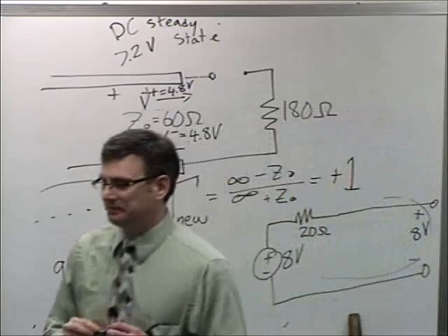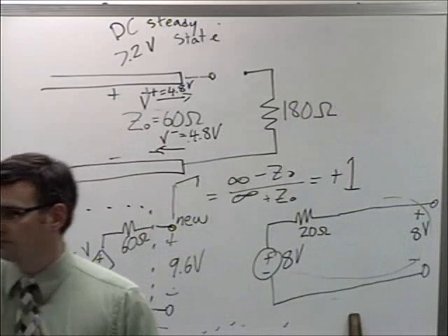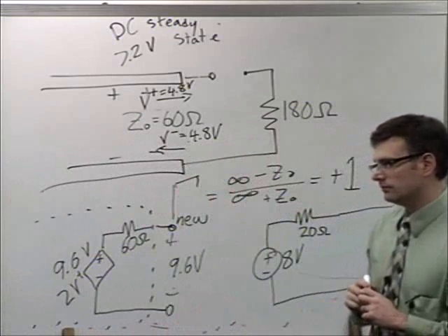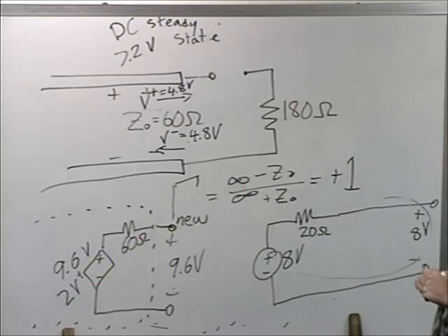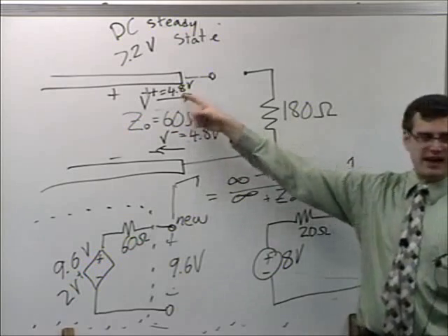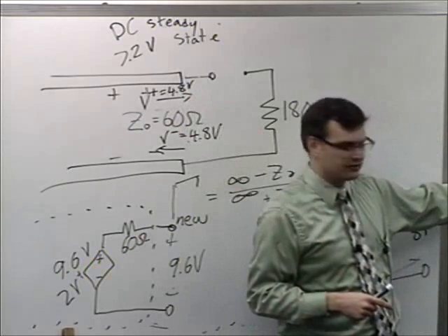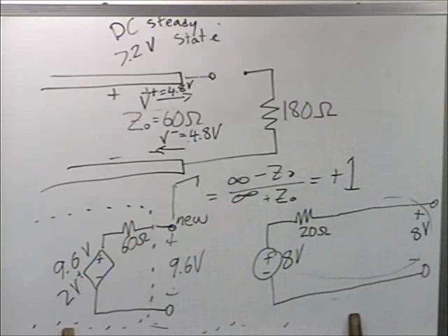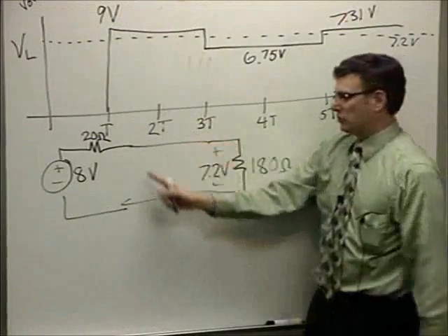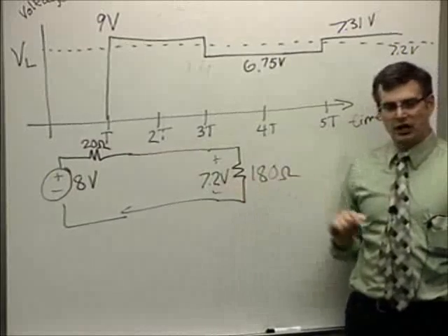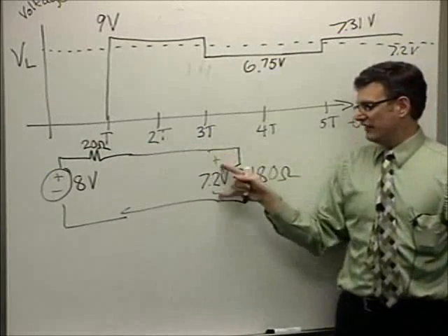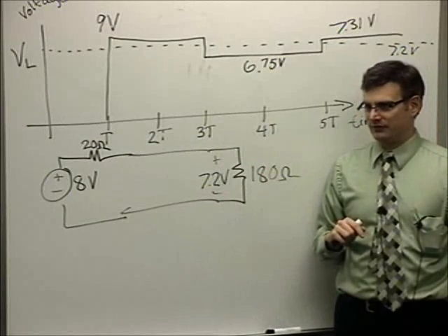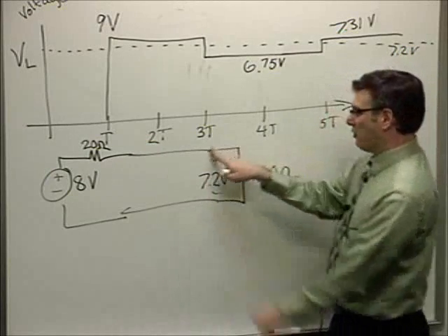Yeah, Lem. I'm not quite sure where you're getting some of your numbers from. Not your solutions, but the ones that you're plugging in with. 7.2, is that given to us as the incoming voltage? So that was the steady state value that we came up with over here, after we had let the system charge up. The system reached this steady state value over here, which was a 20 ohm resistor in series with a 180 ohm resistor. Voltage divider formula, 7.2 volts. And then that was our starting point for when we flipped the switch right there.